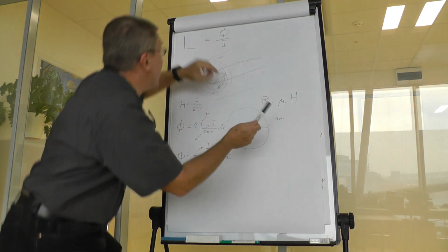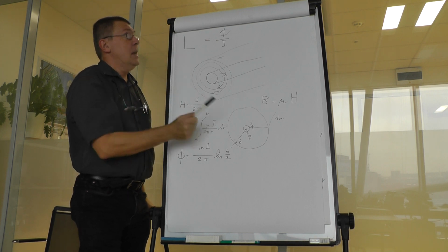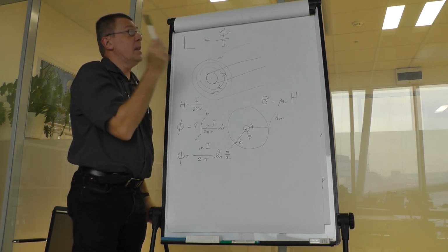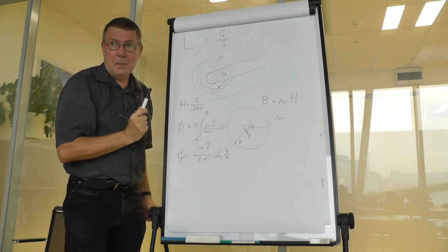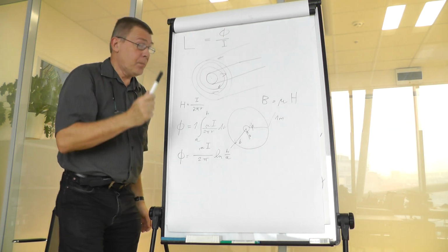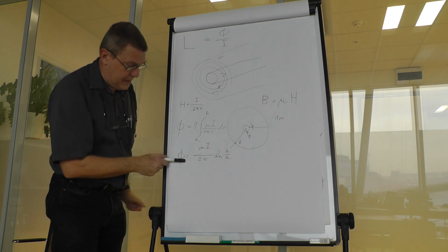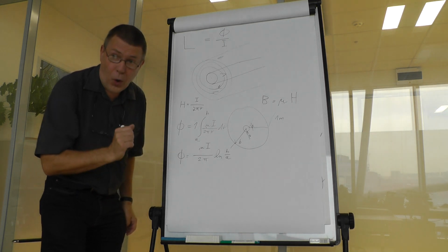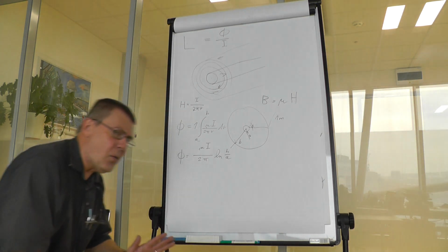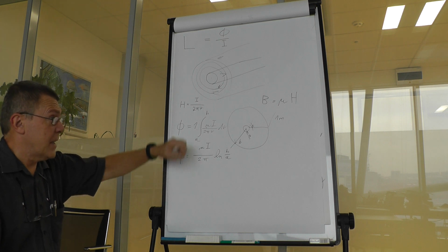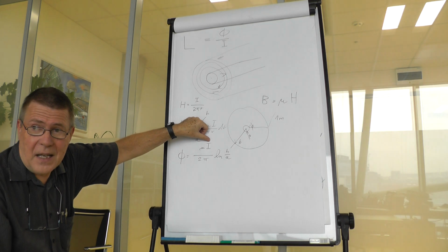And we can return back to the definition of inductance. It's a ratio. In the numerator we've got the flux, in the denominator we've got the current that has created the flux. And therefore, to get the inductance, we just divide the flux by the current. Fortunately, it's a semi-proof of correctness of our calculations. The current in a linear system must cancel out.